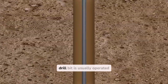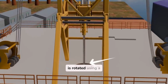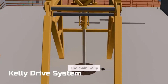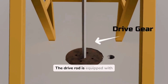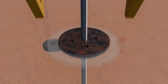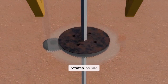In borewell machines, the drill bit is usually operated using high-pressure air, but in oil rigs, the entire drill string is rotated using a drive system called a Kelly drive. The main Kelly rod used in drilling has a hexagonal shape and fits into the drive rod. The drive rod is equipped with gears that can be rotated by an engine or motor. As a result, when the drive rod turns, the Kelly rod also rotates.